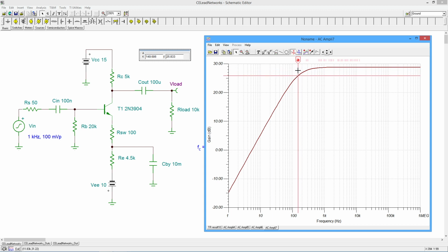Okay, somewhere around there. I'm getting about 150 hertz. So maybe that beta is, in fact, a little higher than what we were expecting, or what we assumed, I should say. We can kind of play around with that, but that is good. It's telling us that, again, this capacitor is going to react against this resistance that we see looking in here.